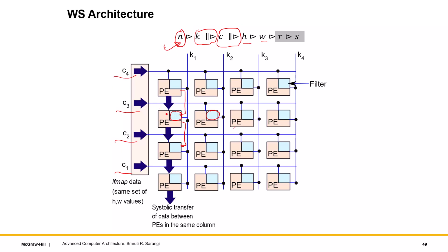So then the job of each PE is to take in input data and compute a convolution with the weights here. That would create a partial sum, partially computed data. So basically the final output is a sum of all of that partially computed data. So what would happen is that the partially computed data would flow from this PE to the next PE.